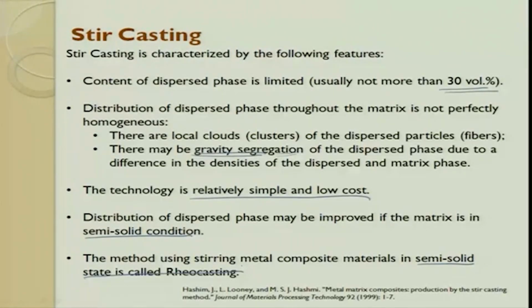Basically, you have a solid, you convert it into liquid, and then freeze it to get back a solid. Rather than doing that, I take a solid and bring it to a mushy state. So I apply less energy, but the viscosity is there. I have to make sure that viscosity plays an important role for dispersion. Keep that in mind, then add the ceramic particle and quickly freeze. By doing this, you reduce the time and also the energy used. But there are other implications which you have to make sure of.